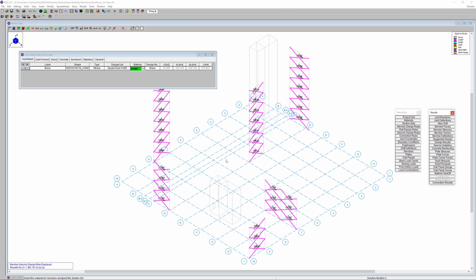And so that gives you, ultimately, more strength, right? You can use that full thickness instead of using that reduction in thickness. If you need more information, the Steel Tube Institute, the STI, is a great resource for that. Also, most of the really big manufacturers in the country are rolling A1085 tubes, so you're not going to have a problem finding them. They're not few and far between. You're going to be able to use them when you want.